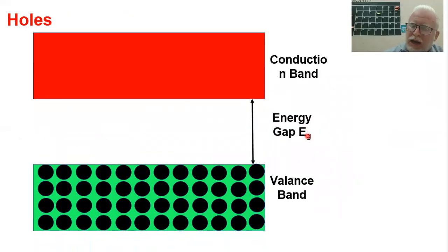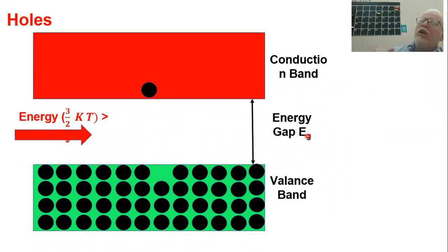We will call these electrons that are in the conduction band by nature, due to the internal thermal energy at room temperature, the intrinsic concentration, if you remember this name, or Ni. For example, Ni for silicon at room temperature is 10^10 per cubic centimeter. That means at room temperature, without any external sources of energy, you can find 10^10 electrons in silicon per cubic centimeter. One of you may ask here a very important question.